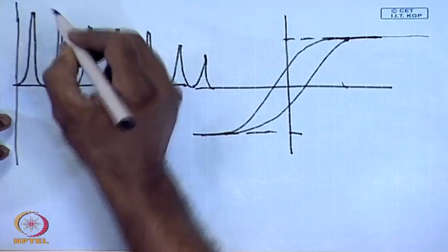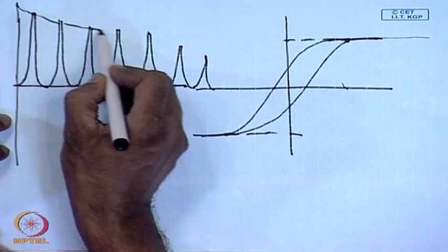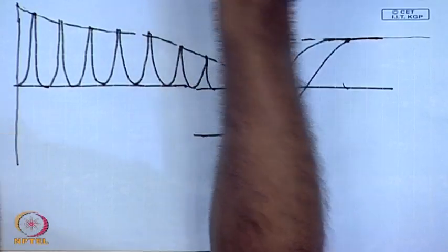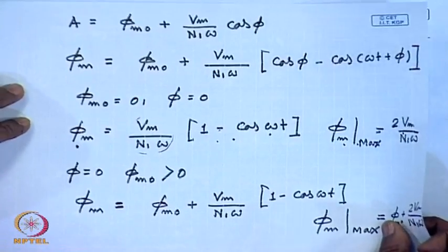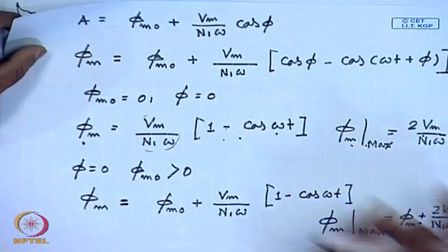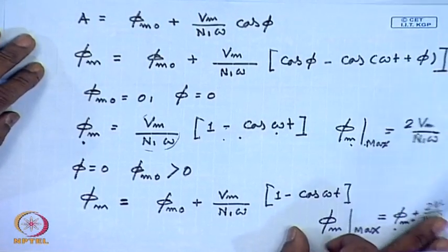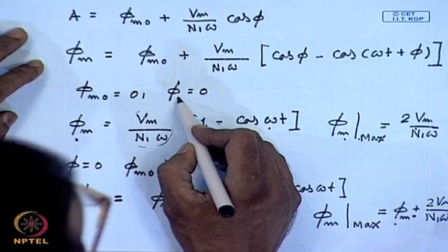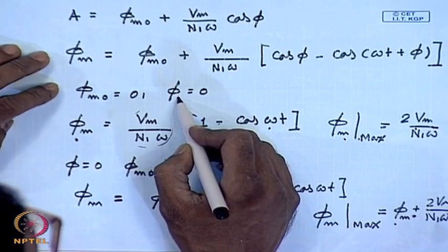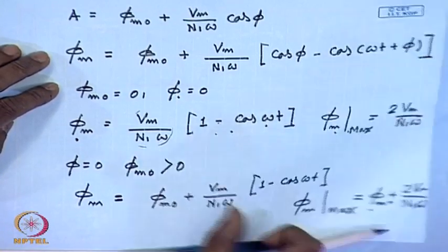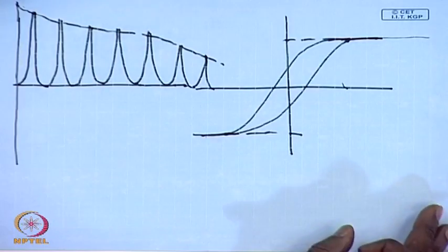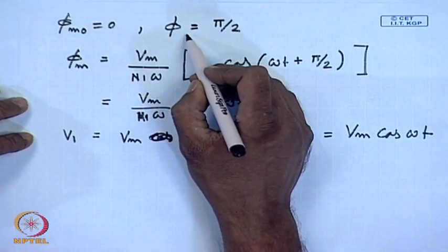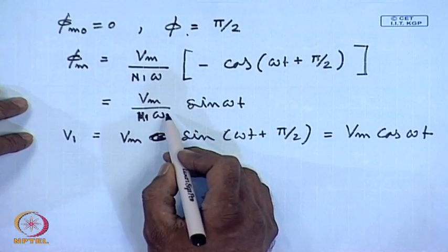This phenomenon is called the magnetic inrush in a single phase transformer, and the severity of the inrush will depend on the instant at which the transformer is switched on. For example, at positive going 0 crossing, if we switch on the transformer, then the inrush current will be maximum, whereas if we switch it on at the positive maximum, there will be almost no inrush current.